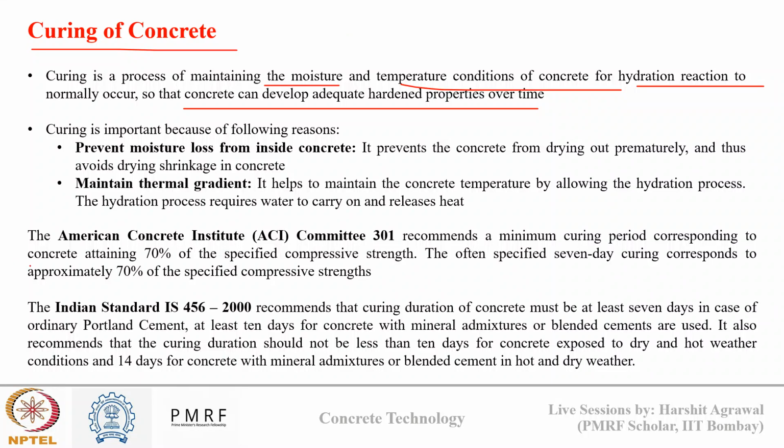Now why is curing important? For the following reasons: it prevents moisture loss from inside concrete. The moisture that is there inside concrete is there for the hydration reaction. If moisture loss happens from inside concrete, what will happen? There won't be much water available for hydration, and it can lead to shrinkage in concrete and improper strength gain. I don't want my concrete to dry out prematurely, and I want to avoid any drying shrinkage in concrete. For that I need to ensure that there is proper curing.